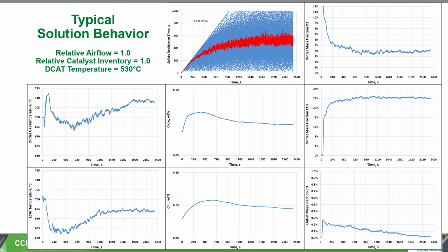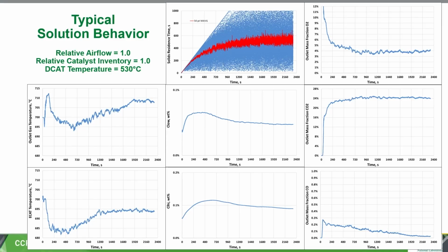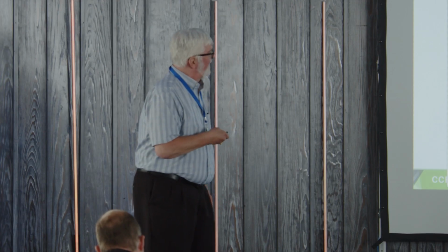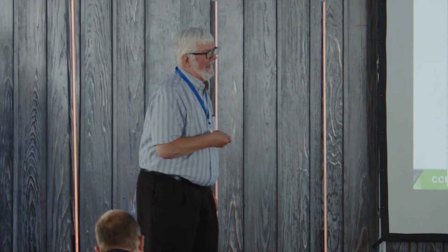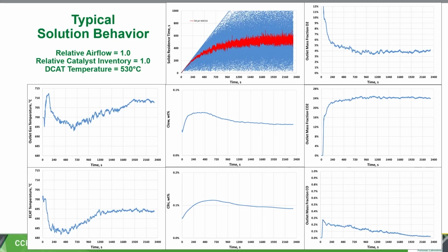But you can see here, this is a 2400 physical second simulation, and you can say, yeah, okay, we're pretty much at steady state there. Even though, it's interesting, the CO is still coming down, right? But don't be too alarmed by this. This is because we've set a real long residence time in this simulation. Although I would love to work with you guys to see if I can speed this up a little bit, because this booger runs about 300 seconds per day. So you're talking about 8-day simulations on my workstation. It's still not alarming because I've got the 3 licenses running and the project's going.